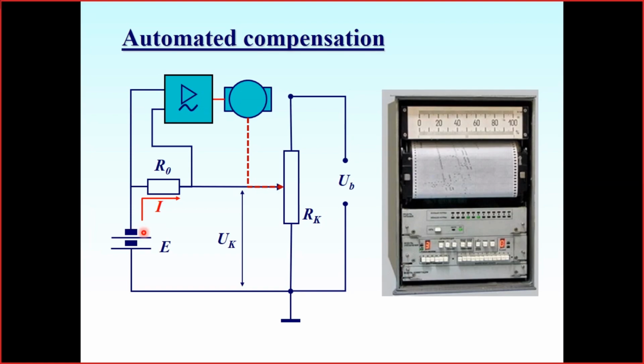Another limitation of the potentiometers is that they use mechanical balancing, so the real motor, which has to provide real movement of the real shaft of the potentiometer, is quite inertial. So we couldn't use them to measure very fast processes. So this is a limitation.